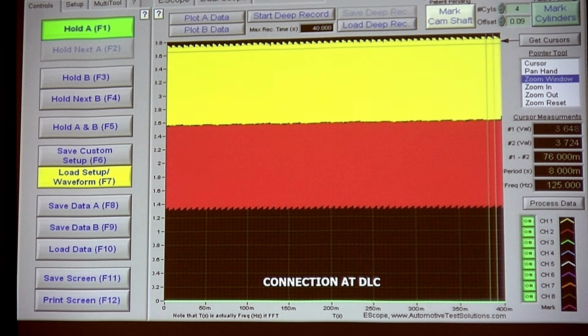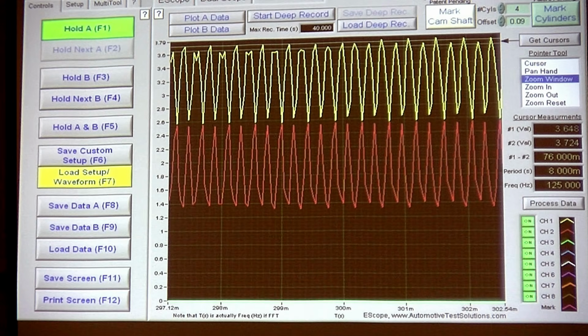Now, we looked at this on a Ford, and a Ford is directly wired to the bus, isn't it? So if I put a box on the DLC, I'm in the bus on a Ford. Does that make sense to everyone? So let's look at this waveform. What's that? It's ringing, echo.